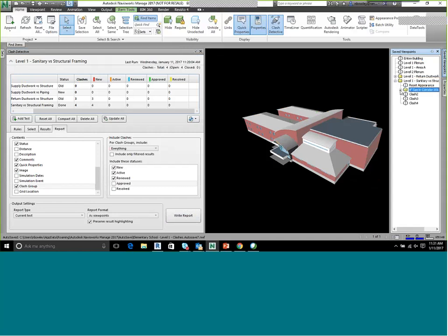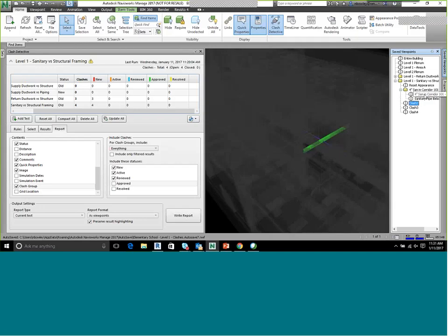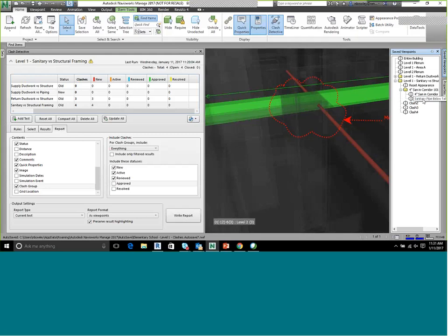And if you had some logical grouping, again, items would be grouped together in a nice order that kind of helps you identify, hey, these are all the same clash really. They all get resolved at the same time. So you don't have to keep looking at different clashes that are already resolved. That makes that nice folder structure. When you name your clash, so remember I named this one clash, sanitary pipe below tall beam, 4-inch sanitary in corridor 101. That naming comes into your save view inside of Navisworks.